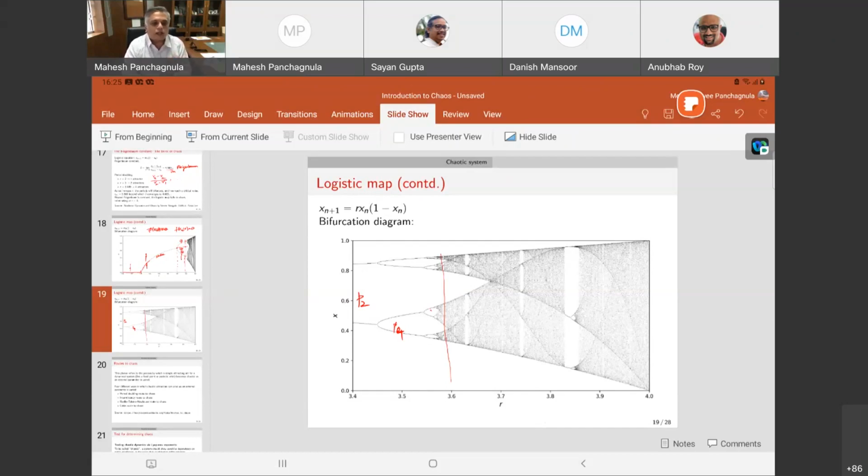People have done analysis of experimental data to show that, at least they show that it's just a sequence of period doubling states that results in this chaotic state called turbulence, and that there is nothing inherently random about it. So fundamentally, if you're doing computational studies of a chaotic system like Lorenz was doing, you really cannot compute error due to finite precision. What you do know is the Lyapunov exponent. You can compute the Lyapunov exponent.